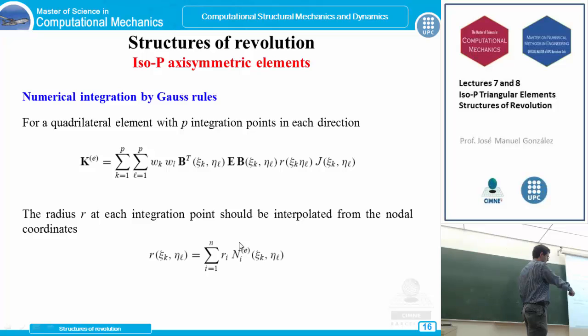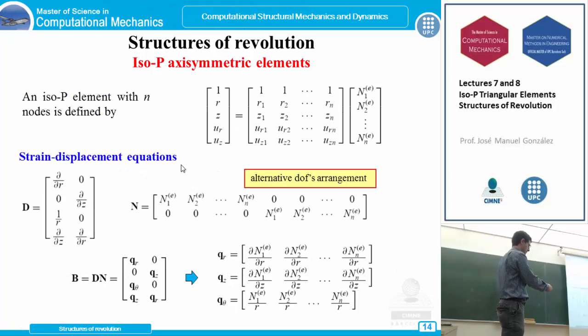So imagine that we have this N shape function here, which changes the order of this polynomial expression inside the integral. And besides, we have a small problem again, because inside this B strain displacement matrix we have this vector here, these expressions here. In general, we will have a shape function divided by r.